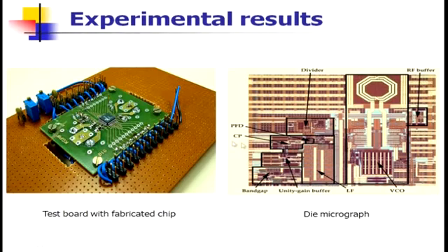If you look here, this is the completely fully on-chip frequency synthesizer, with the inductor and so on, and this is the divider and the buffer. You can see the buffer, the band gap, the PFD and charge pump on one side, and the capacitance block. This is the complete die micrograph. Clear? So, this is how you are improving the performance step by step.